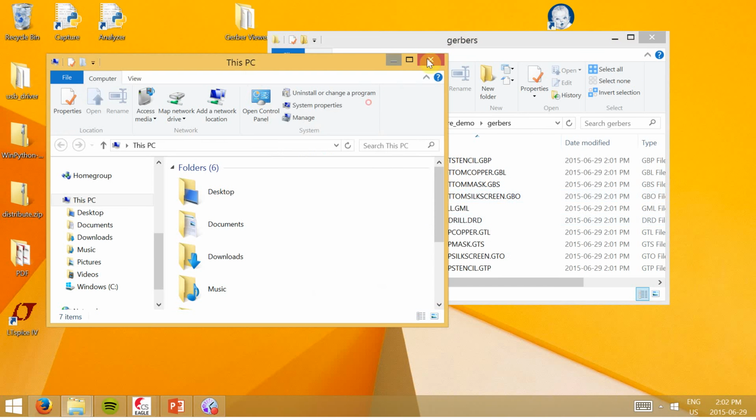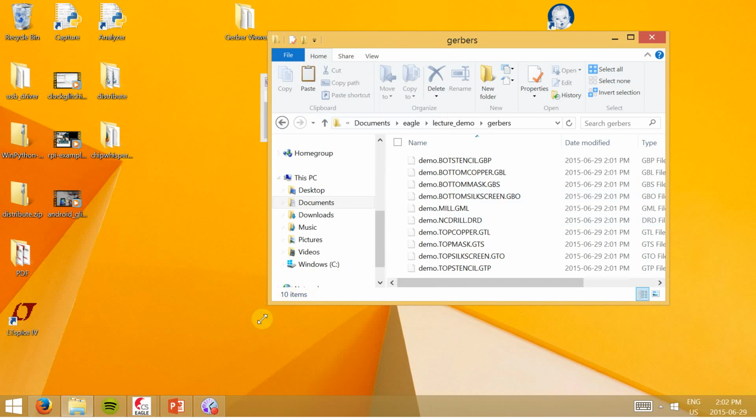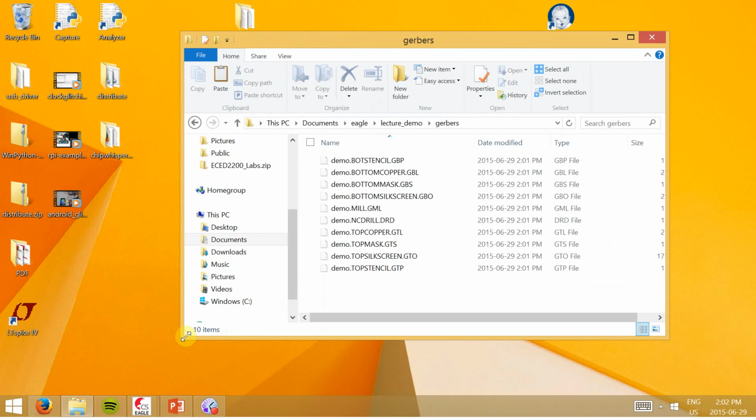So this allows us to actually open them with a Gerber viewer, because these files include everything a manufacturer needs to build their boards. In addition, there's 2 extra files here I didn't talk about. There's this top stencil and bottom stencil, so not Silkscreen. Be careful of the names. I'm just going to delete them.